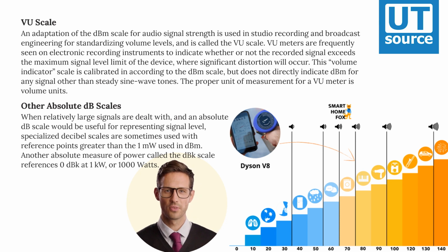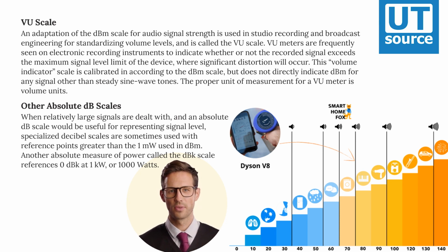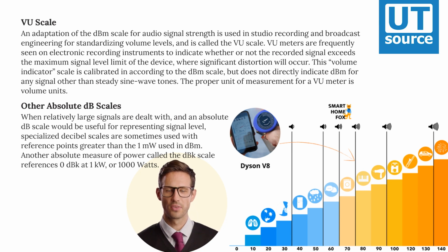This volume indicator scale is calibrated according to the dBm scale, but does not directly indicate dBm for any signal other than steady sine wave tones. The proper unit of measurement for a VU meter is volume units.